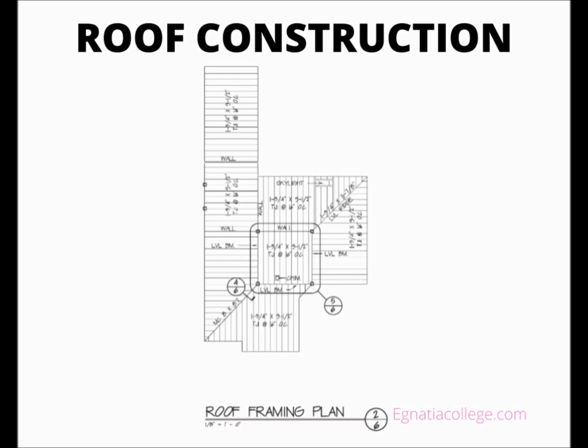The roof frame may also include collar ties. Collar ties are usually made of 1 inch, nominal thickness, lumber. They are normally included on every second or third pair of rafters. This information should be shown on the roof section if collar ties are planned.